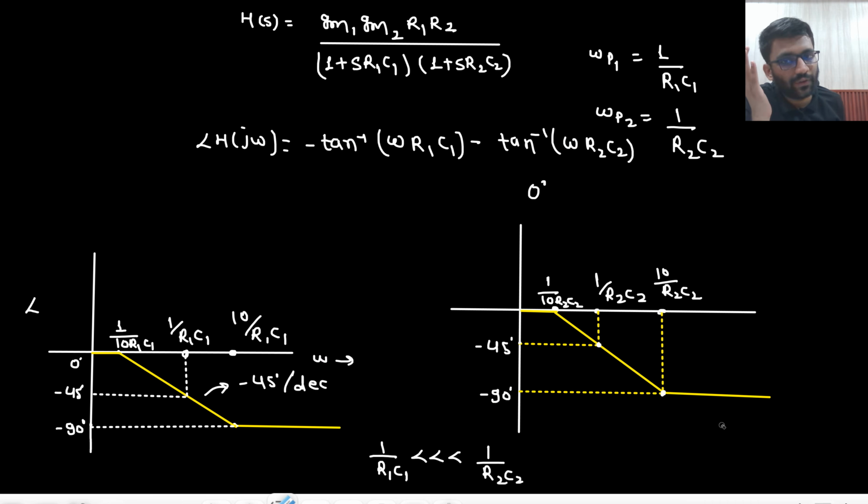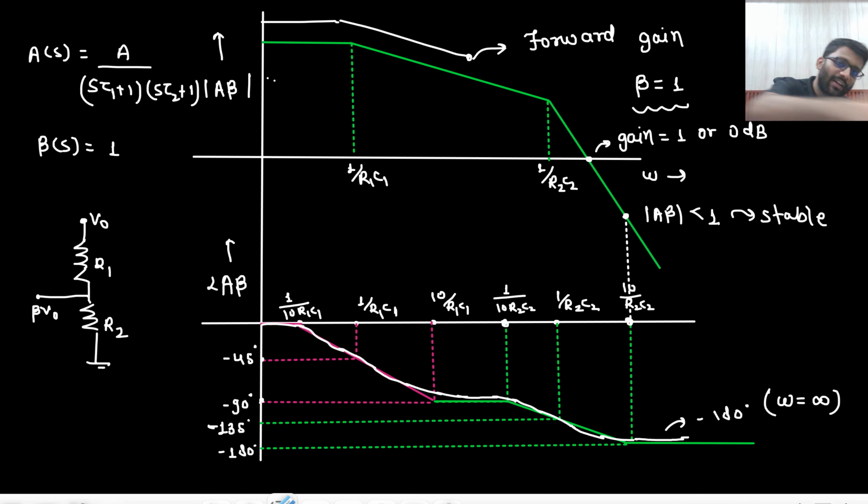So at omega equals to infinity, certainly there will be greater roll off, and then it will keep on rolling off. So certainly at omega goes to infinity, the gain would be lesser than 1 only. So it is 100% sure that this system will be stable. Are you getting this point? Unless your forward path is providing any phase shift, basically this forward path is providing me this phase shift, and this is the Bode plot. As per this Bode plot, this system will be 100% stable.